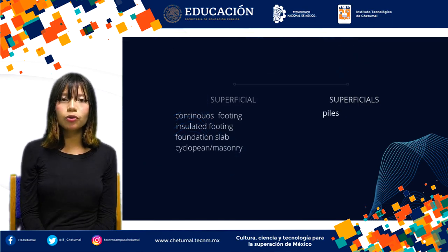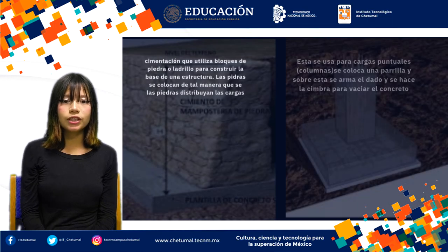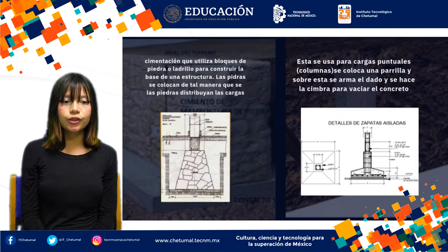Pedestals are small but crucial structural elements in foundations. They are used to transfer the loads from columns or pillars to the foundation, whether it is an isolated or continuous footing. Use and characteristics. Pedestals are reinforced concrete blocks placed directly below pillars. They are smaller than footings, but their role is to efficiently transfer the load to the base of the foundation.